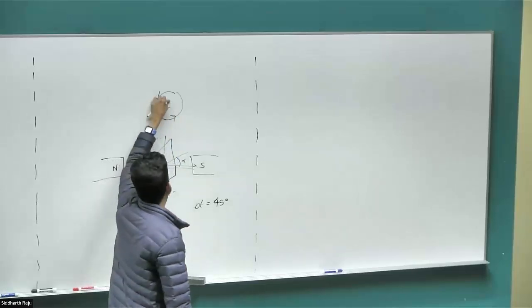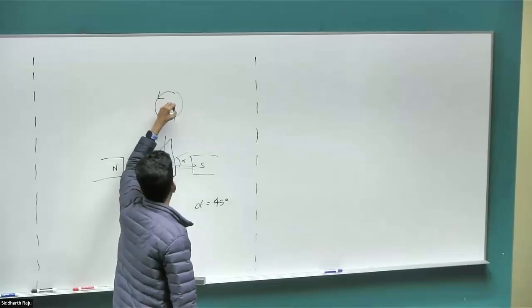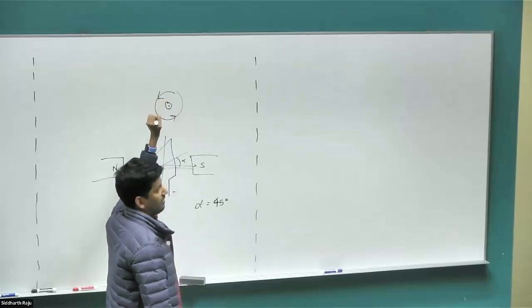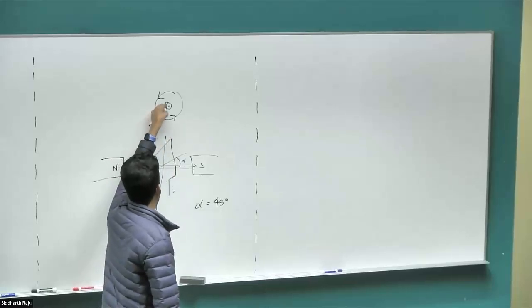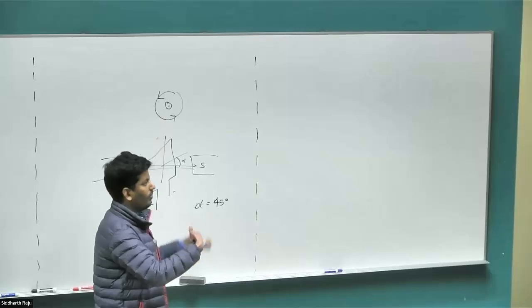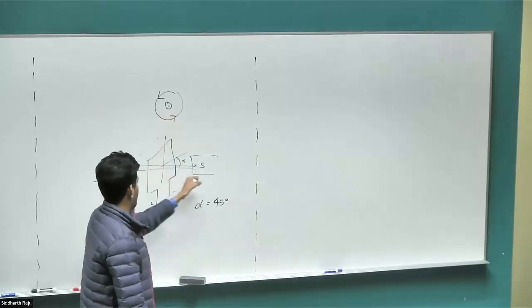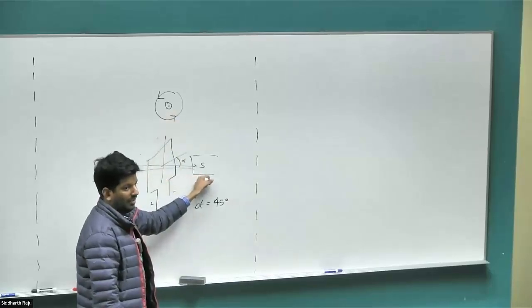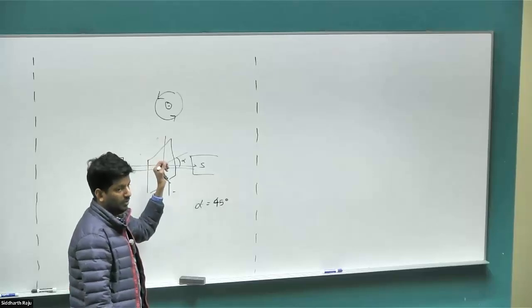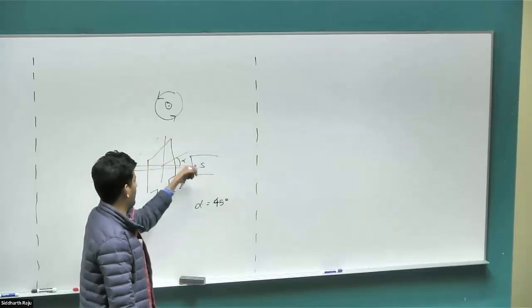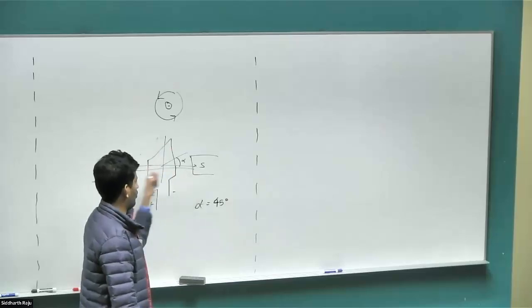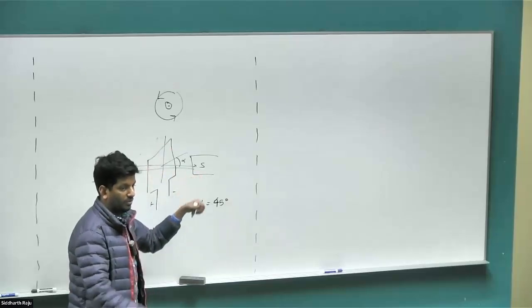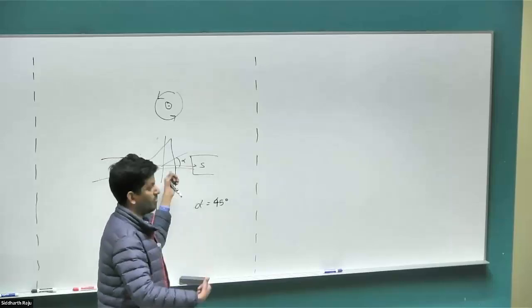Right? If I just give you this diagram and ask you what is the source of it, you can confidently say it's a current carrying conductor right in the middle. So the magnetic field is created by this conductor, then you can apply the thumb rule to create this. But here the magnetic field is created by an independent magnet, and the coil is something totally independent of it. Right? It's going to experience this magnetic field, but that is not the source. The current in this coil is not the source of this magnetic field. Right? So the curling your hand, that doesn't apply in this case.